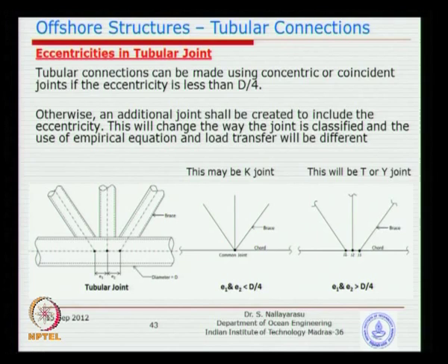A typical example will be, you see these 3 pictures. On the left side you see basically this similar type of joint, with the work points at the intersection of braces and the cord member. Now if you model like this, what really happens is the load carried by one of the braces will be cancelled by another brace. That means one may be in compression, the other in tension, which means the cord is not actually experiencing the shear transfer from one brace to the other brace.